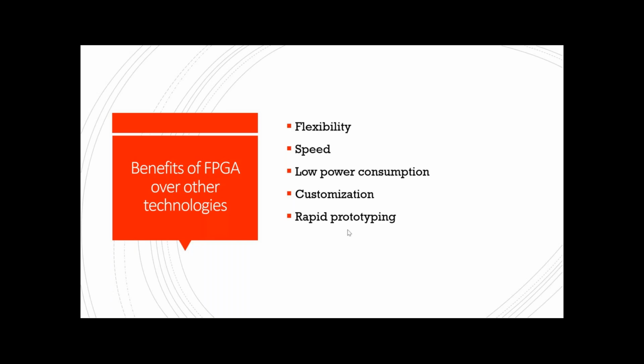If I consider one FPGA with something like 10,000 lookup tables, even if I implement a simple AND gate or a complex FFT algorithm, that FPGA will still have 10,000 lookup tables. So there will be some lookup tables unused, and routing wise also, it's not as simple as your ASIC, right? But again, it's kind of a trade-off. So which to use, ASIC or FPGA, right? It is based on the application and production.